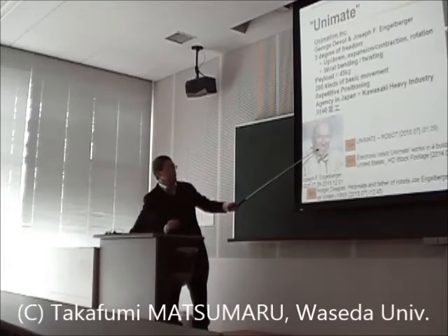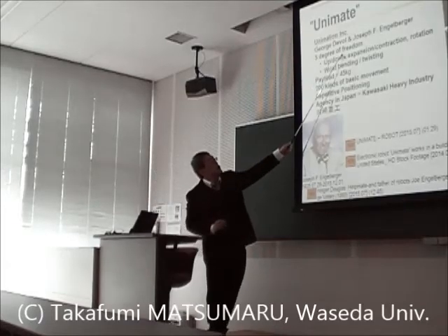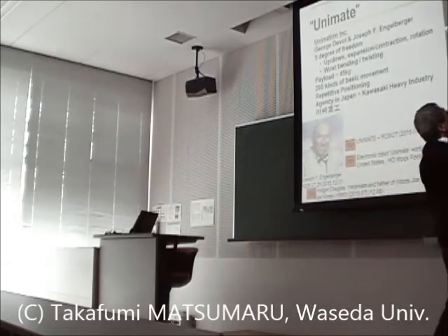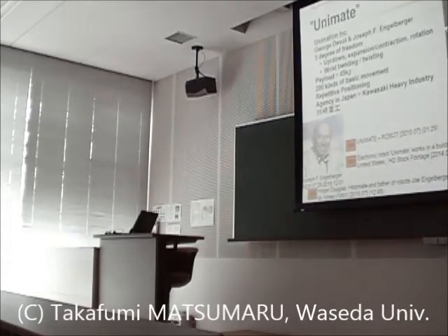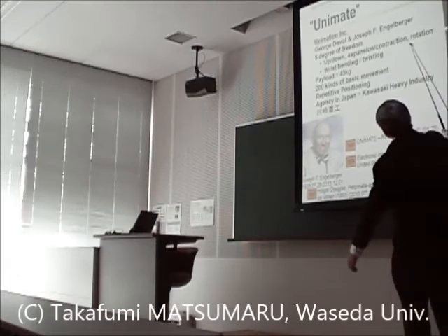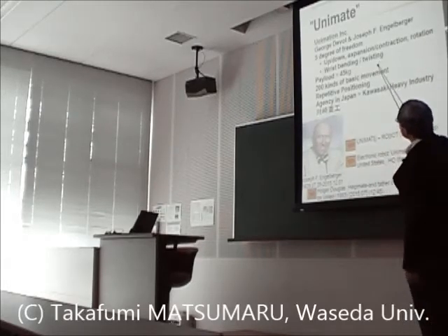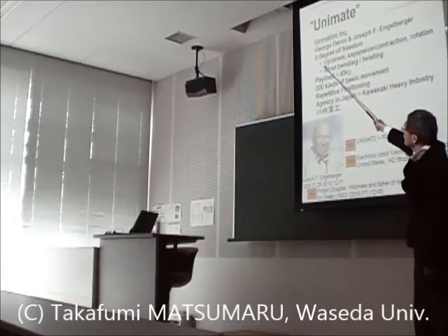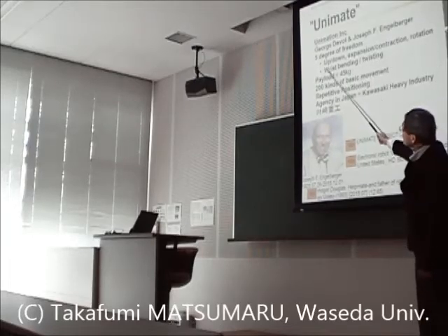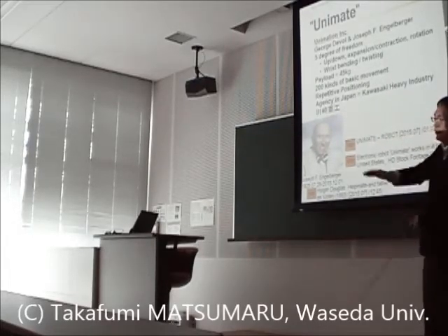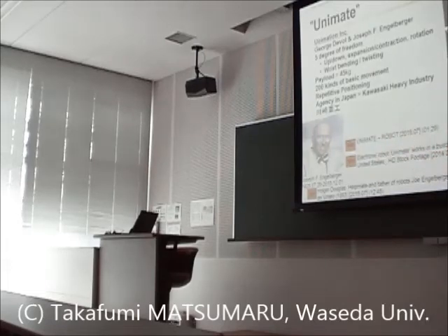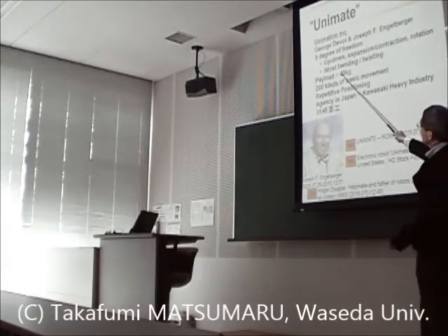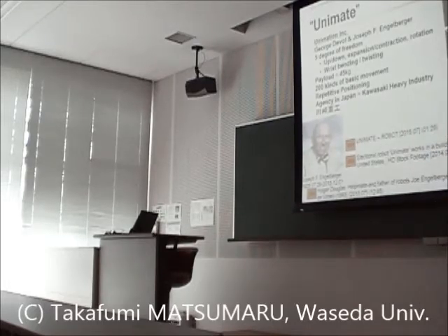It has five degrees of freedom: the base and swinging up and down, a third joint with linear movement, and a two-joint wrist, with expansion, contraction, rotation, wrist bending and twisting. So totally it has five degrees of freedom. This part is for wrist positioning, and this part is used for wrist orientation definition. Payload is about 45 kilograms.